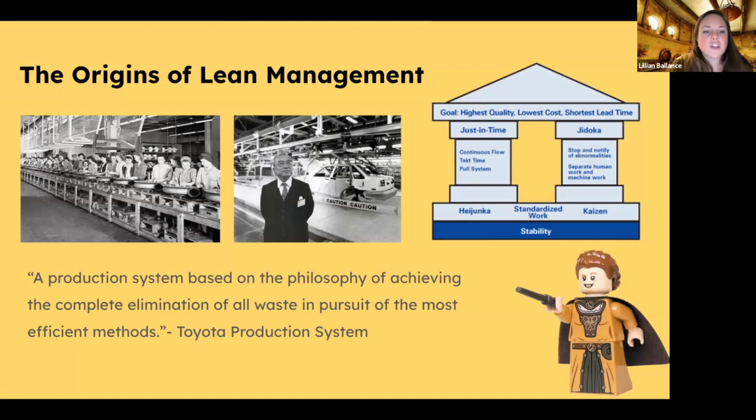The Toyota production system is based on two concepts. One, Jidoka, which is translated as automation with a human touch. So when a problem occurs, the equipment stops immediately, preventing defective products from being produced. And two, the just-in-time concept, in which each process produces only what is needed for the next process in a continuous flow. With the grounding in these two philosophies, the Toyota production system can efficiently produce quality vehicles one at a time.